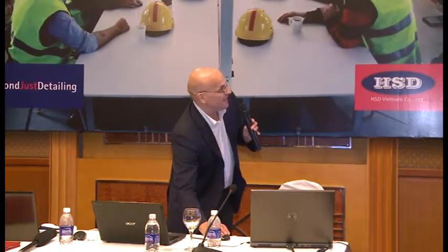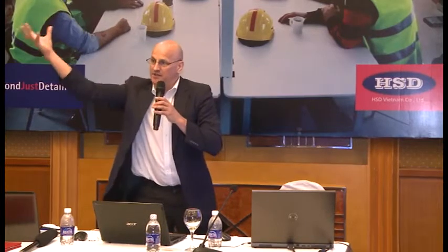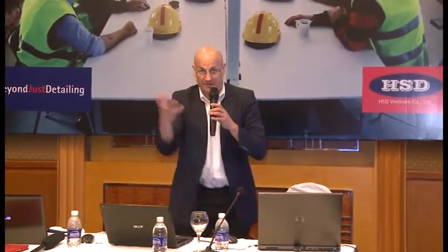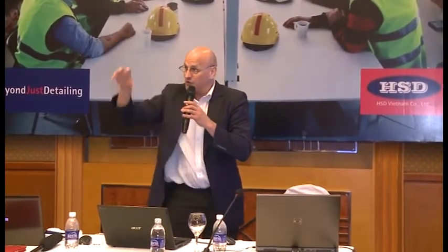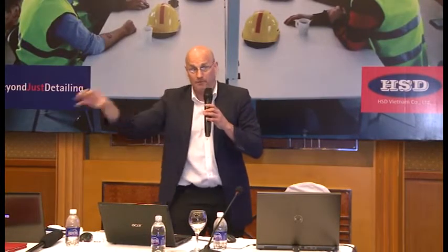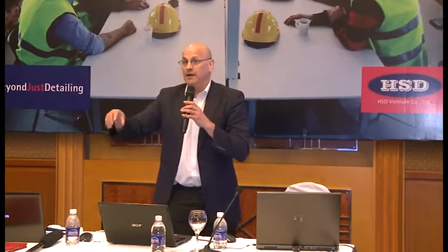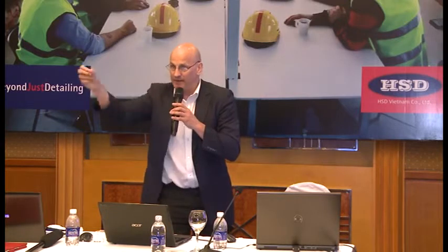Okay, let's just start this going again. Now, when Simon actually accesses that model, what happens is it makes a copy of that model onto his PC. A copy of that moment in time. When he changes it, it uploads the changes to the cloud. So each person has got a local copy of the model. In multi-user, each person is accessing the model over the network.